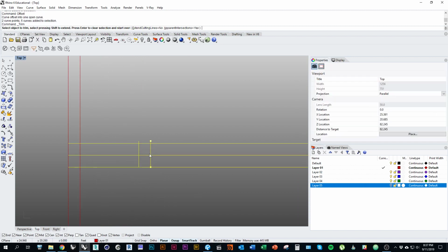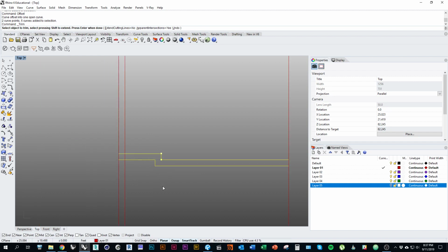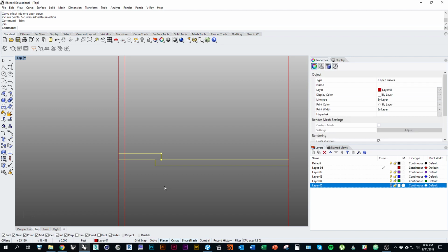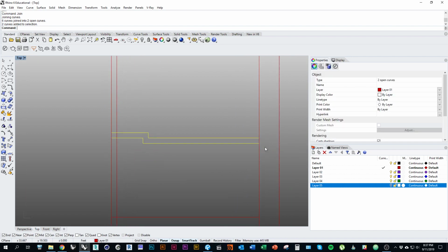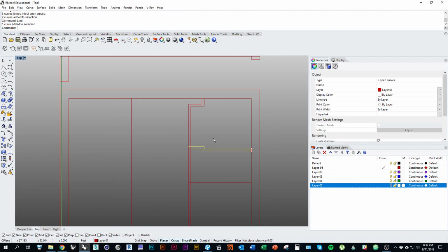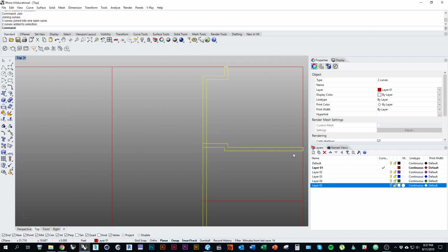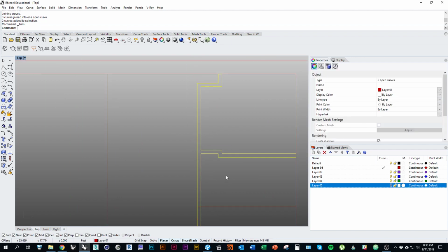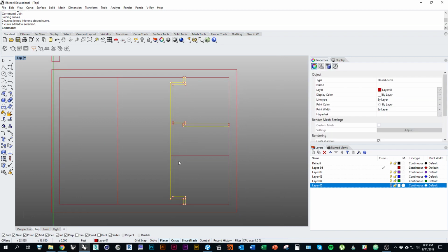And then I'll just select all my lines and trim them, and join them. Oops. Press enter to end the trim command, and type in join to join them. What I'm actually going to do here is make an end line. So I'll draw a line over the 2 ends that connect to this wall, and join those all together. And then I'm going to select my original wall and this new wall and trim the overlaps and then join it, so I have one continuous thickened polyline.